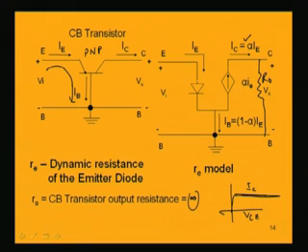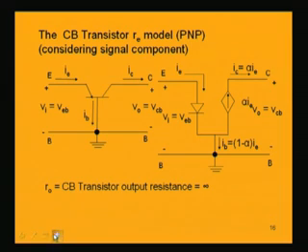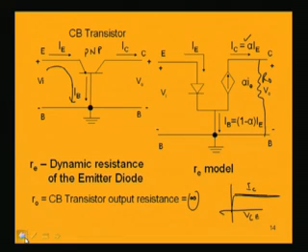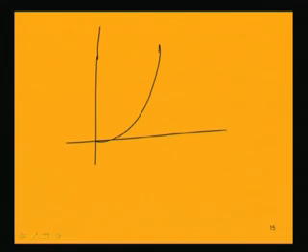So, now if we look into this forward bias diode, it is not right to keep it like this, because we have to find its equivalent and replace it by the relevant parameters. So, if we look into this forward bias diode and remember the input characteristic, then we can replace this forward bias diode by a resistance, which is the dynamic resistance of the diode. Because if we consider the input characteristic of the diode, it is a characteristic like this, that is input current IE here versus the emitter to base voltage, that is what we are having in the input characteristic, VEB and IE.